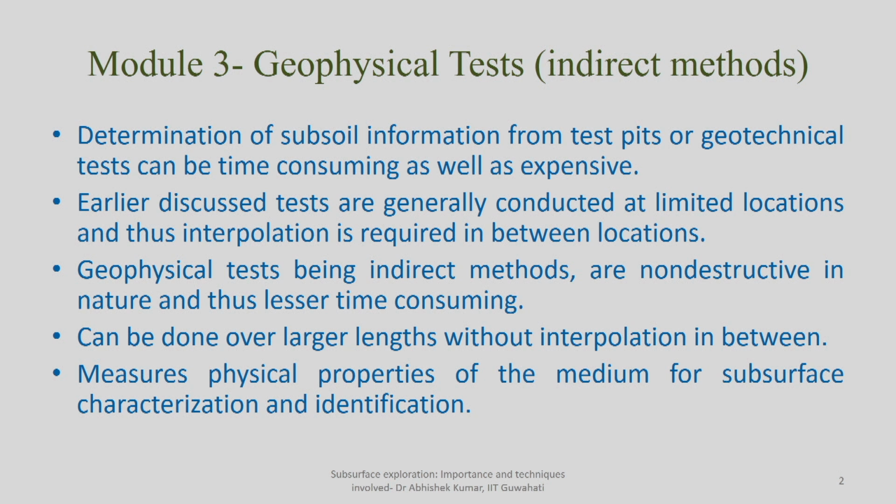So, whatever your site of interest, depending upon the guidelines provided for different kinds of structures, for different kinds of field investigation, even for different kinds of seismic zones and areas, in geotechnical investigation the entire area can be divided into a number of grids, and for each grid you have to conduct at least one or more than one test. At times you have to validate the findings from a geotechnical test by one more test. So, that we have discussed.